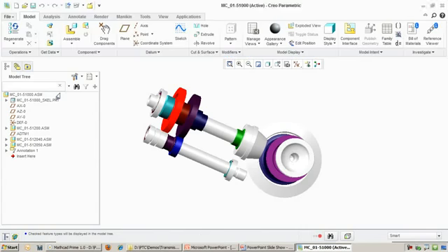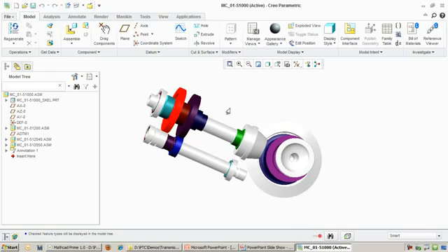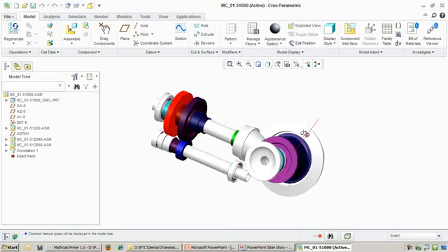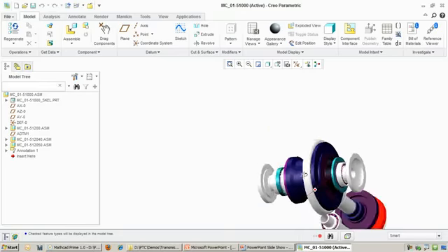Let's take a look at this assembly in Creo Parametric. For the ease of visualization, we have removed some of the gears on the shafts so we can focus on just one gear pairing. As you can see in this assembly, we have the input shaft on the bottom driving the output shaft on the top, which is in turn driving the differential on the right. In this particular gear, the driving gear has a radius of 23.5 millimeters, and the driven gear has a radius of 65.76 millimeters. We want the shaft to be able to deliver 250 horsepower of power while spinning at 2000 RPMs.